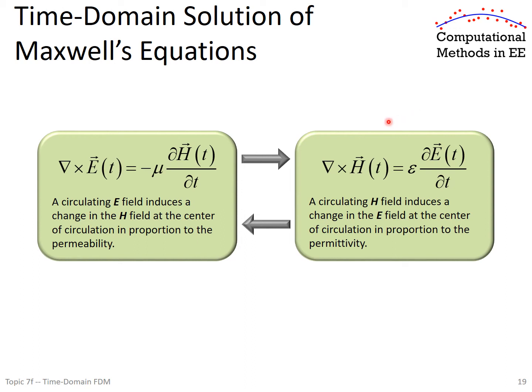So in this first step, we're updating H based on the curl of E. Now, very similar in the second step, we will then calculate the curl of the H field and update the electric field based on the curl of H. So we update H based on the curl of E, then update E based on the curl of H, and then we go back and update H on the curl of E, and it's a back-forth algorithm, sometimes called a leapfrog algorithm. So it's EH, EH, EH, EH, and it's constantly bouncing back and forth. And this iterates over time. Now, each one of those equations also has a little tiny loop going over space. And that's the heartbeat of finite difference time domain.